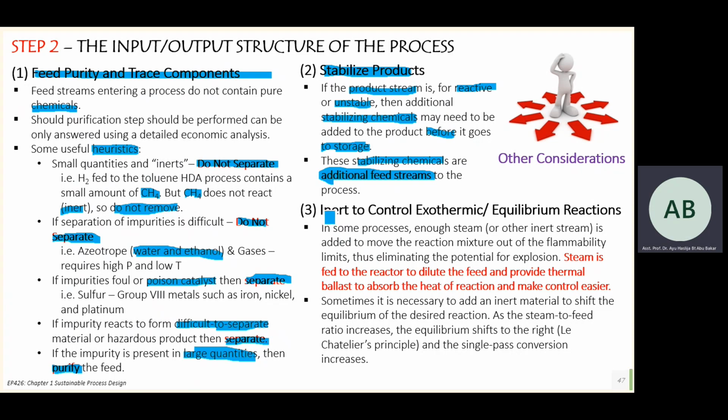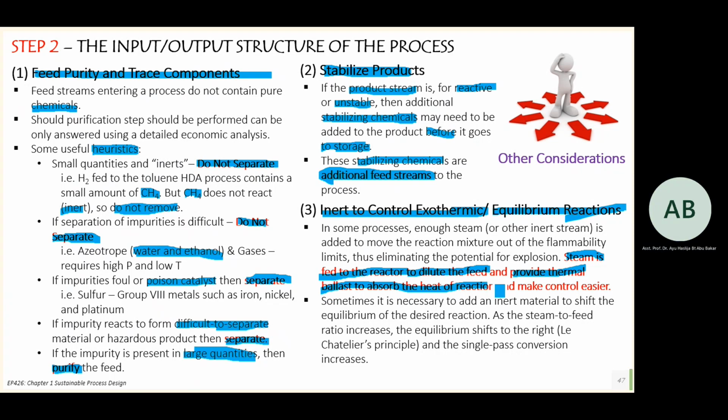Okay, third one, inert to control exothermic or equilibrium reactions. In certain processes, steam is fed to the reactor to dilute the feed and provide thermal ballast to absorb the heat of reaction and make control easier.